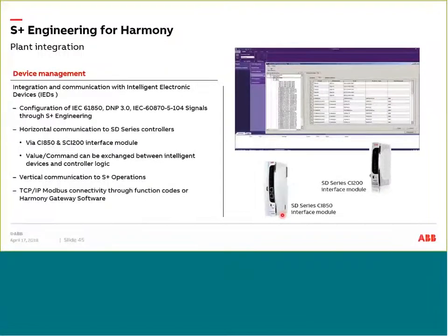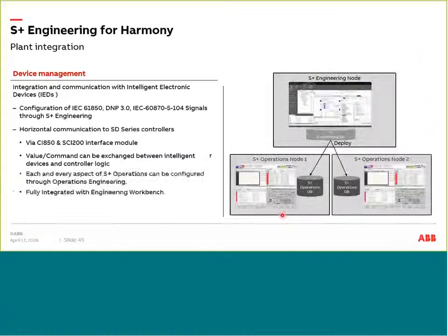So we can integrate these devices within S Plus engineering as well. S Plus operations is at a higher level where you're looking at only from a scalar standpoint, but if you want to do operations, if you want to control or bring those data for control, we have various tools and software available. One is the CI850. So many of our users are now going into 61850 integration, electrical integration, and bringing it back into the DCS. So we do that with a lot of our users, and we have a card which is called the CI850 to bring it into S Plus engineering. We can do DNP 3.0, IEC 104, of course, Modbus, TCP/IP, and various other protocols can be brought into S Plus engineering from a control standpoint.